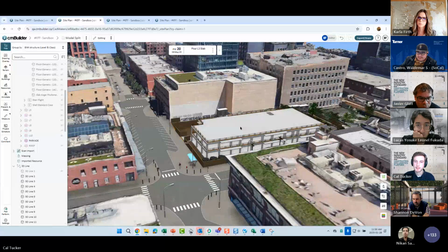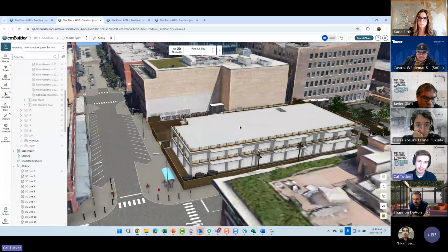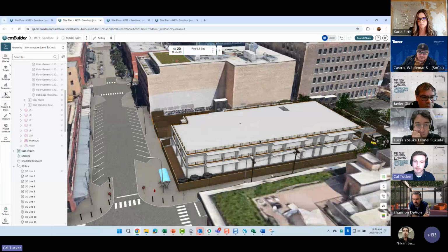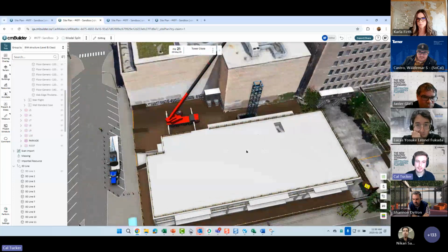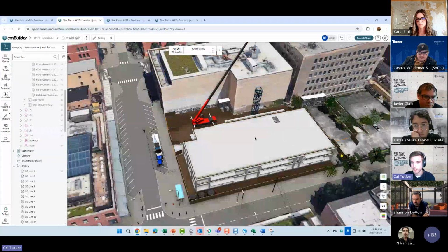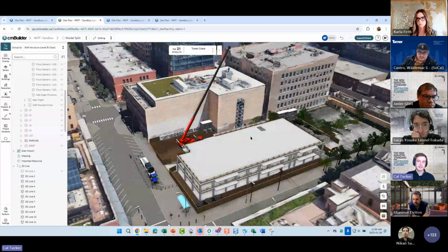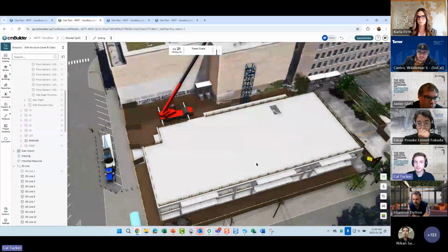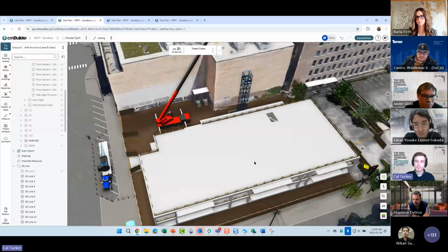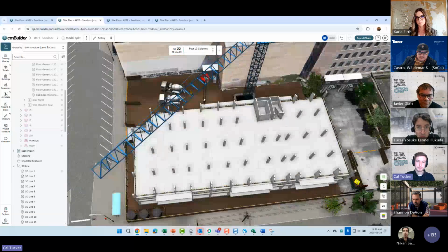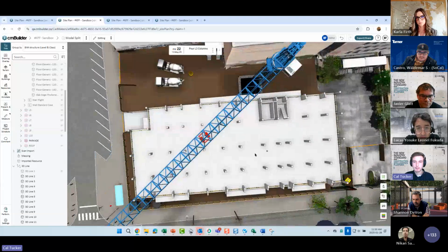Yeah, absolutely. So what we have here so far is just like a preliminary schedule. You can think this could be for a tender for your initial schedule. But as you start thinking about this job a little bit further, you kind of got to think about doing pour breaks, getting the quantities of the concrete you need on a particular day, as well as just the more nitty gritty of how you're going to pump the concrete, which might not be relevant for a tender.